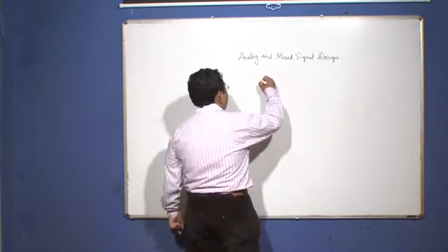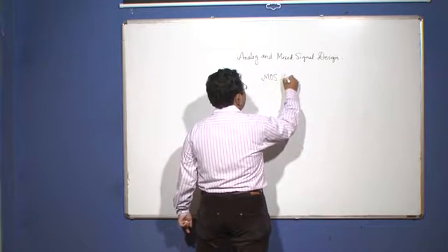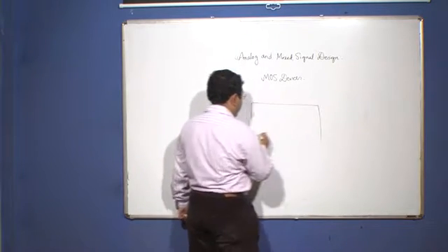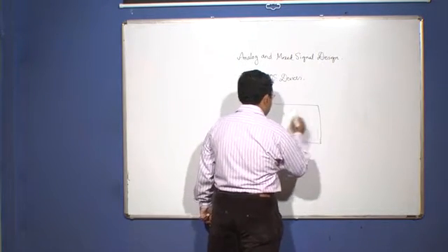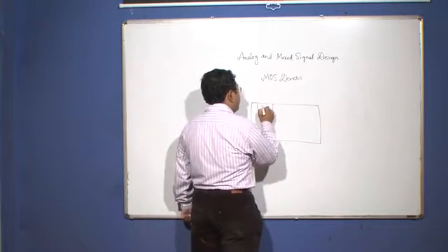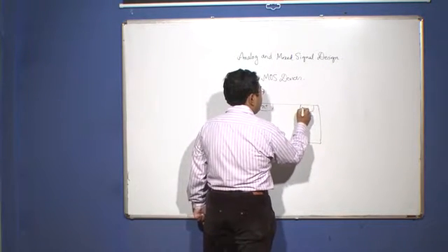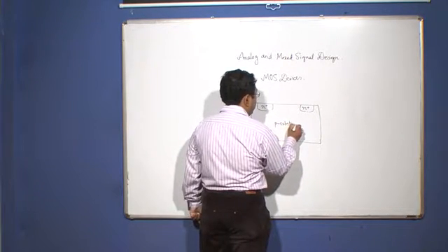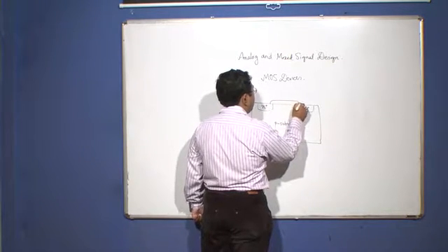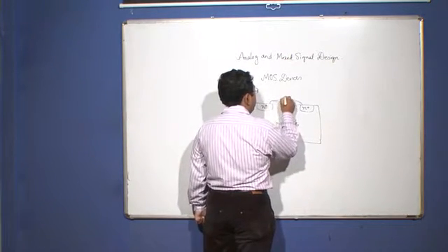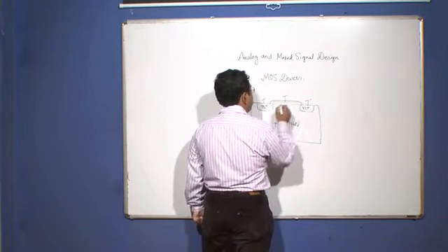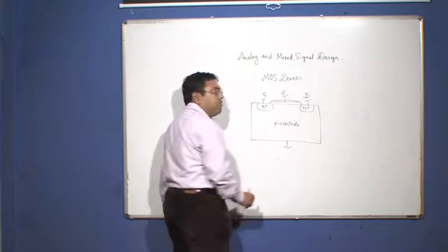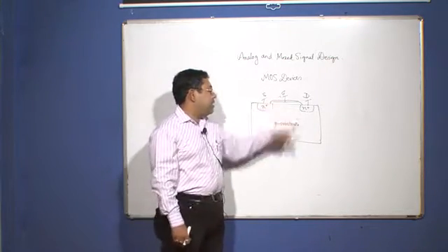So, first we shall talk of MOS devices. Just to have a quick recap of the behavior of MOS devices, if I consider an NMOS transistor, then it consists of a p-type substrate with two densely doped N diffusion regions on it. Then you define the source, gate and drain, and so a MOS, as you know, is a 4-terminal device. So, you have source, gate, drain and bulk.